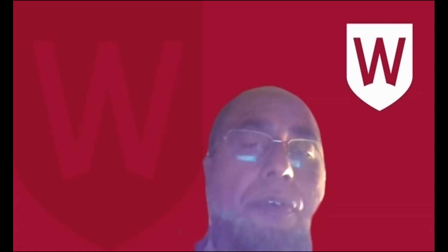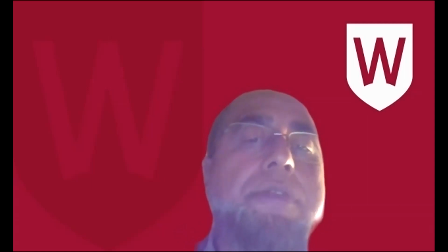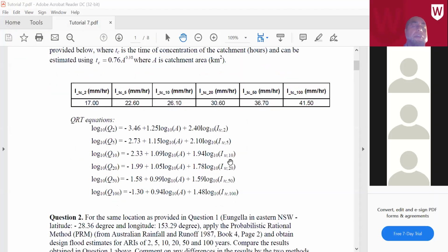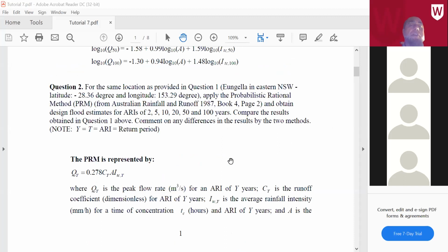Okay, so I'm going to share my screen here. The next question is, for the same location as provided in question one, apply the probabilistic rational method from Australian Rainfall Runoff 1987, Book 4, page 2, which is the old version of ARR, and obtain design floods for 2, 5, 10, 20, 50, and 100 years return period, average recurrence interval.